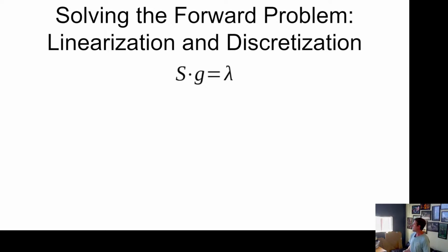And we also have to assume that the response between each pair is linear to the amount of actual permittivity material between those electrodes. So this is a pretty gross simplification of this problem. There are a lot of higher order terms to this equation that we're just going to ignore, and you kind of have to in order to make this a tractable problem.